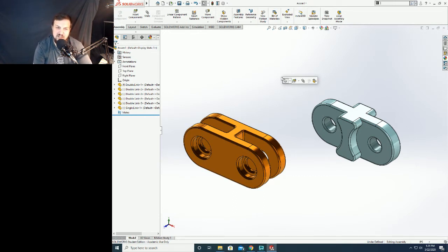If you remember back to our parts, that changes versus, like, our 3D model space, which gave you things like boss extrude, cut extrude, revolve, sweep, all of those. And in our sketches, it gave you line, circle, square, all of those. So in this one, it's going to give you a different set of tools yet again. It's going to give us the insert component tool, which is what you click on to drop new components in. Then it's going to give you the mate tool. So that's the second way to get to the mate tool.